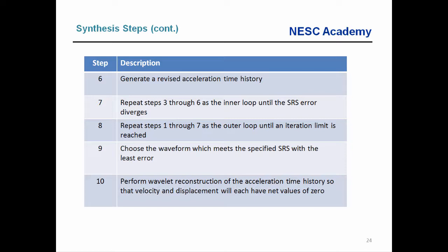So what we want to do, as part of this process, and this comes into play with step 9, is come up with an acceleration time history that, of course, we want to "simulate", I put simulate in quotation marks, an actual pyrotechnic shock event. We want it to satisfy the SRS, but we also want its corresponding velocity and displacements to each have reasonable, stable values, and preferably with net zero displacement, net zero velocity.